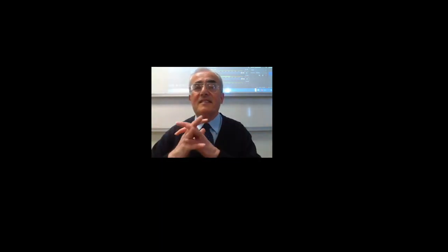It is like a uniaxial test specimen. Not the same, but similar. It is going to be a rectangular prism. And for such a loading, that problem can be found in the first chapter of a strength of materials course. Okay, create the model of that object in Inventor. And then first, using the classical stress analysis tools of Inventor, perform the analysis and check, for verification purpose, whether the results are the same. So conclude that, okay, this means that the program can be used.